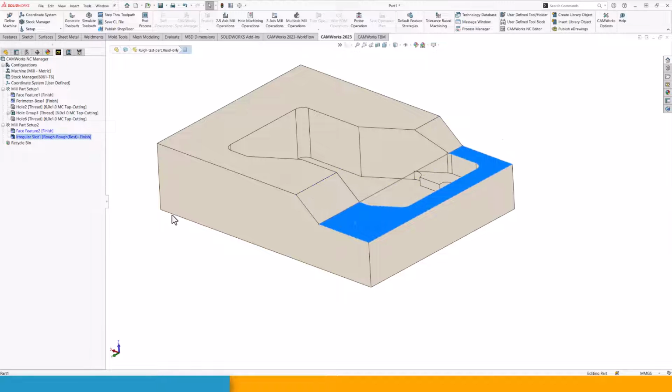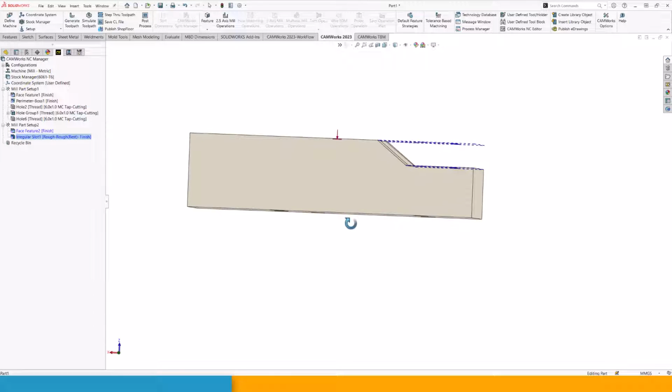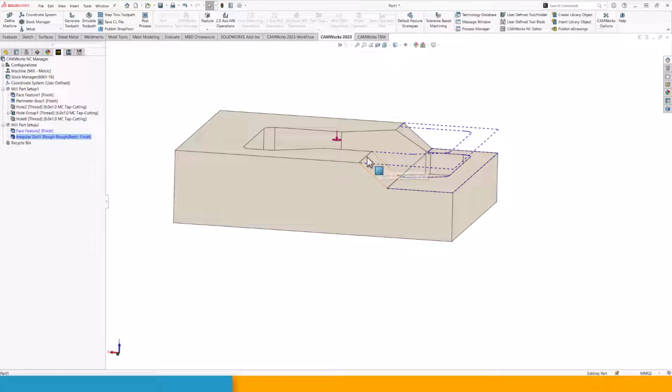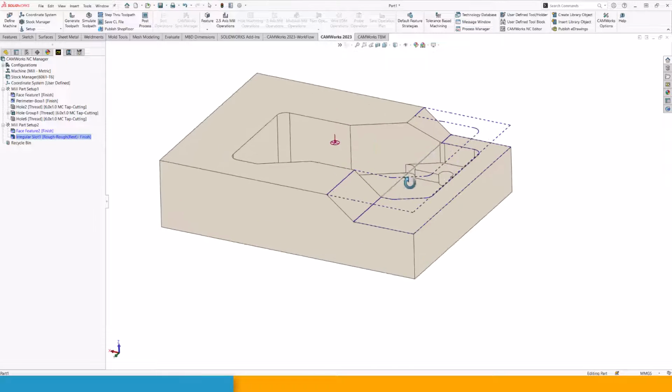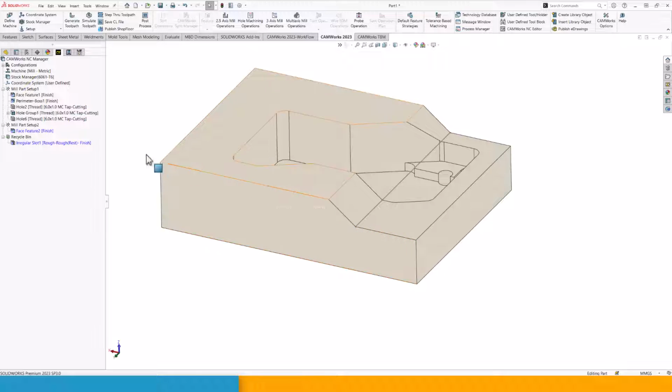And we can see that this is going to find an irregular slot, and you can actually see that it's flowing quite well, following that wall. Now, it is not bridging this edge, and I really don't like that it doesn't. So I'm just going to delete this one again. So off you go. And I'm just going to keep this in my recycle bin because I don't want this to be recreated by mistake if I do any rebuilds later on.